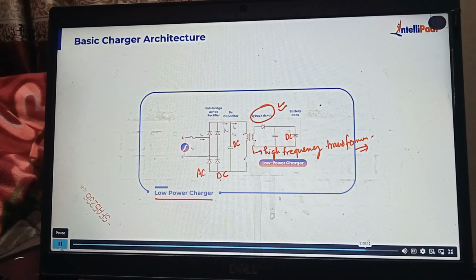please do remember. Sir, I am confused. After the DC circuit, the middle of the transformer is there. So after transformer and diode, I think this is the half-wave rectifier circuit. So the diode is only used to make current flow in this direction, because this is a unidirectional charger, remember. In flyback converter configuration, we use the diode so that when it becomes forward biased, energy can be pushed from this transformer to the battery. But at the same time, it will become reverse biased when the battery tries to discharge itself. Try to understand. So no power will be pushed from the battery to the transformer.